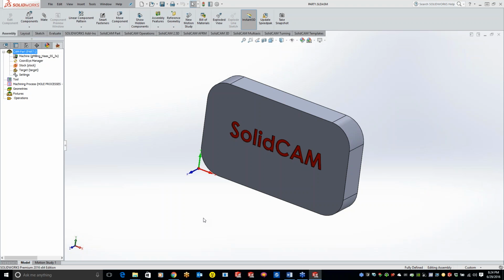Do we have any questions so far on external of SolidCAM, or how it works, or anything to do with that? Yeah, Kevin, we've got one here. It says if you lose the SolidWorks parent model, like you are the victim of Windows 10 stupidity and have to re-image your hard disk from a week's old image, but the PRZ file is on a shop computer and you can get it back, can you uncompress after the fact and get your model back? Yes. So if you're trying to get your model back, and Michael, let me know if I'm answering you right.